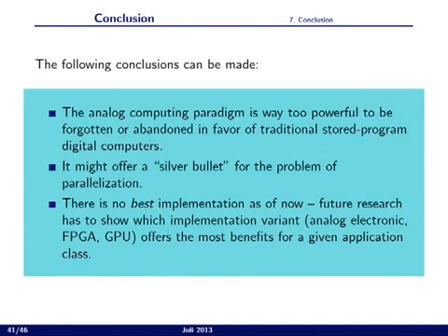You could easily solve a differential equation by applying the structure of an analog computer to an FPGA. There's no need to parse a sequential C program and guess where the parallel parts are, and then derive parallel code for a VHDL description of an FPGA. It would be much simpler to implement a DDA and just see the differential equation you want to solve as a special problem you want to solve on this machine.